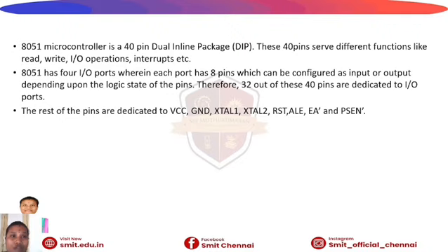The 8051 has four input output ports, wherein each port has 8 pins which can be configured as input or output depending upon the logic state of the pins. As we already know, the 8051 microcontroller has 32 input output pins, so 32 out of 40 pins are dedicated to the input output ports.